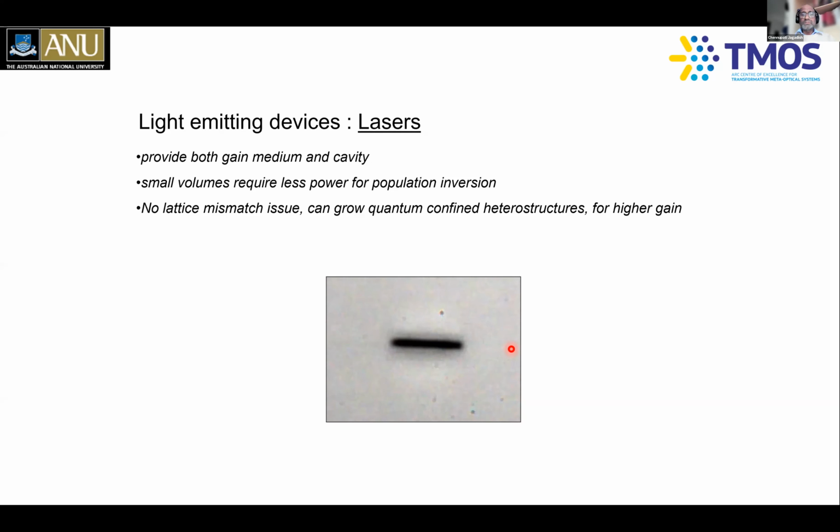Okay. If you pump these nanowires, and you can create population inversion, then you'll be able to get excellent performing nanowire lasers. And that's what our aim has been. Because these are 3-5 semiconductors, and direct band gap semiconductors, they also have very good gain. So they act like a gain medium. They also act like a laser cavity, for example.